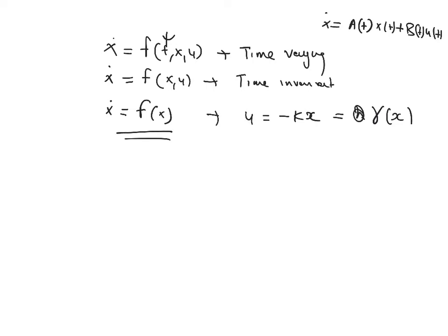So we can focus a lot of our time on this kind of system, x dot equals f of t, x, with no input involved, and ask whether the system is stable or unstable, because u can always be chosen as a function of states. The same stability definitions will come, whether bounded input bounded output, or the autonomous system being stable itself.